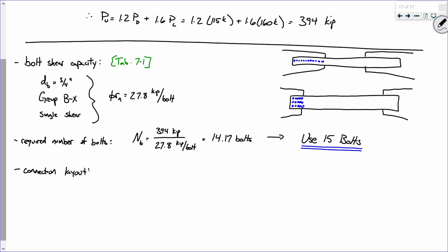Well, there's 3 inches, but there's also something that code specifies. What's the code specify? How do you calculate min and max bolt spacing? 2 2/3 bolt diameter. Okay, so that is the minimum bolt spacing. What's the preferred bolt spacing? 3 times the bolt diameter.